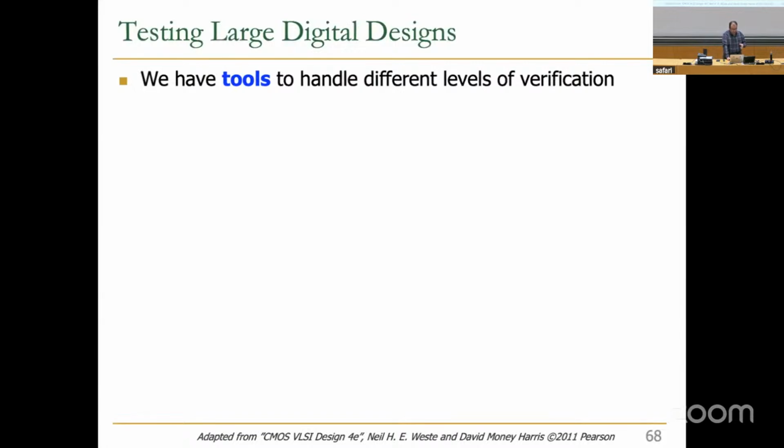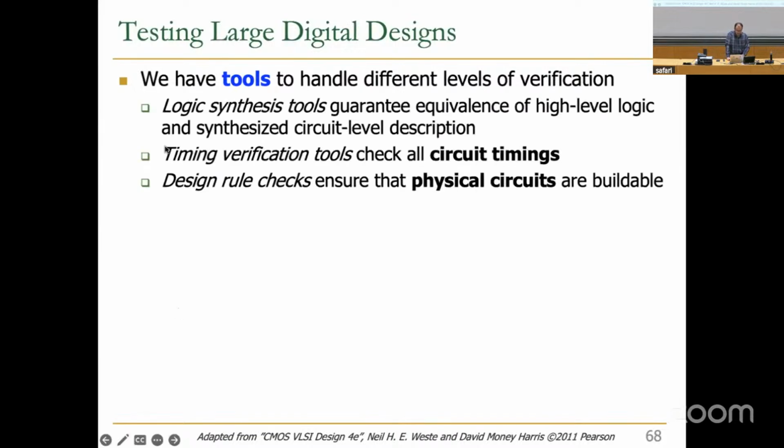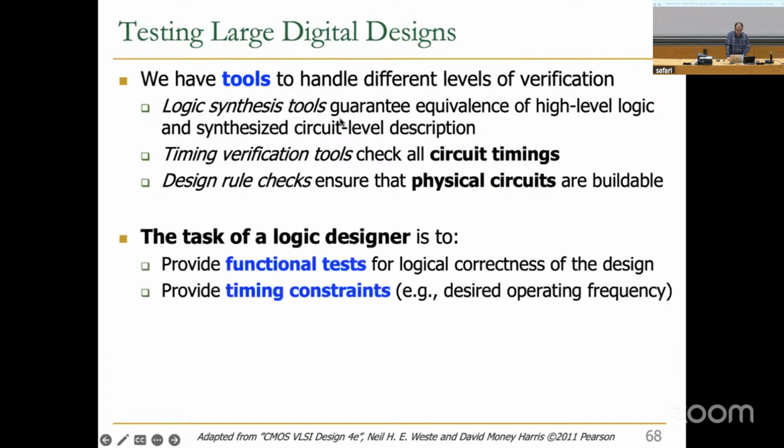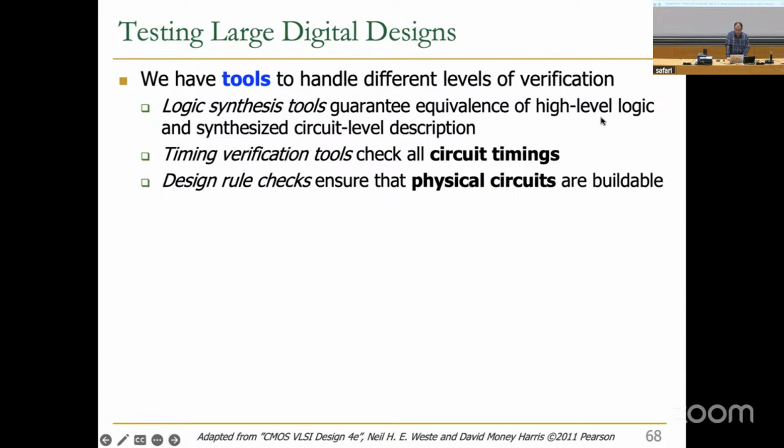So we have tools to handle different levels of verification. We have logic synthesis tools that guarantee equivalence of the high-level logic and the synthesized circuit-level description. That's what I said. In Vivado, when you input your HDL code, there is a logic synthesis tool, though Vivado is not exactly a great example because the tool chain is for FPGA. But for example, take Design Compiler from Synopsys.